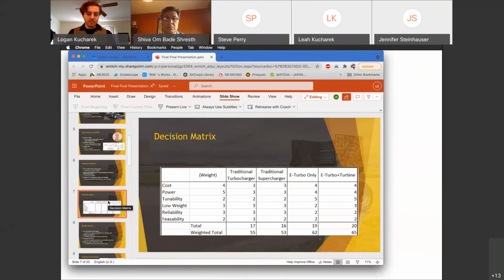In order to do something like regen braking, that would move us into a different category of formula competition. That would move us into a hybrid competition, which isn't what we do. Right. So something similar to that would be where we would use the turbine connected to an alternator. Yeah, great stuff. And I think with that exhaust turbine, that would allow you to remap your boost independently of engine RPM. Yep. And that was the original goal, that theoretically we could have 100% boost at 0 RPM if we really wanted to. We didn't want that specifically.